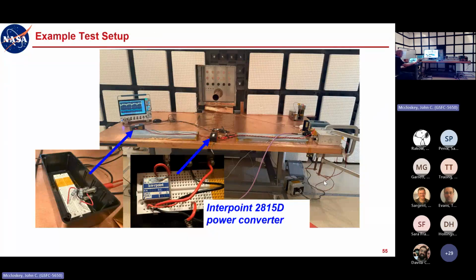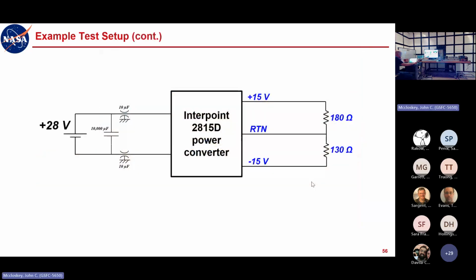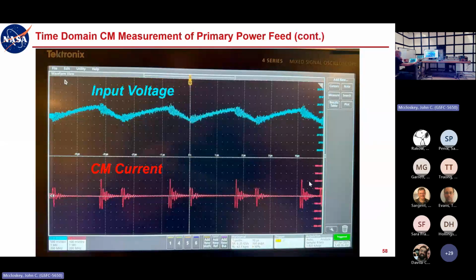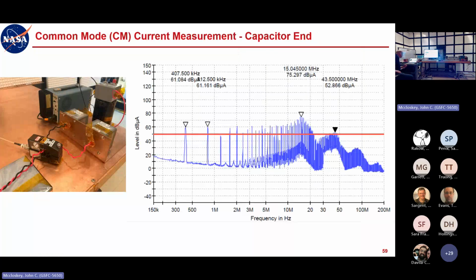Okay, so these are some pictures of what we've been doing here. There's the schematic. All right, so we looked at the time domain. The time domain signals, all that ringing, are still working on a 400 kilohertz fundamental frequency, right? So we would still expect to see a harmonic train of a 400 kilohertz fundamental. So that's exactly what we see.